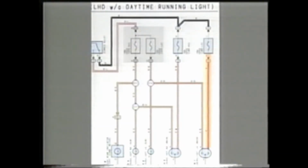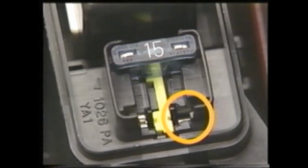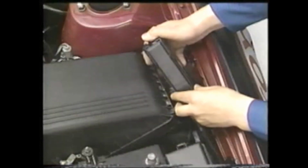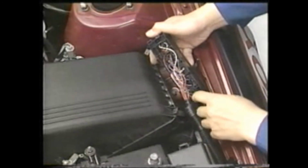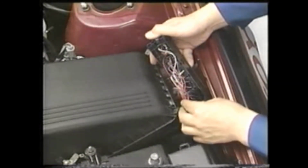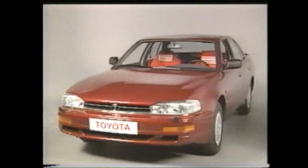Let's check the continuity in this circuit. Well, it looks like the terminal is not fully inserted. We insert the terminal. And then we check the headlight. Now it's operating normally. Let's go to the next example.